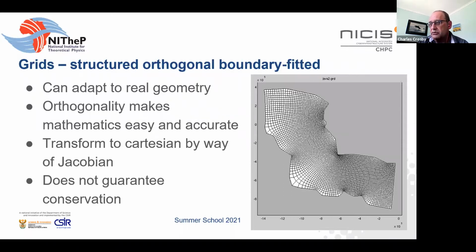So I was talking about this maybe being two coastlines with a piece of water in between, or some kind of two-dimensional flow channel. That's not really relevant at the moment. The point is, this is a single block orthogonal boundary fitted grid. So you take those words individually. It's a single block grid, just like the previous one was. So it's got a certain number of I dimensions and J dimensions. It's orthogonal. It's not rectilinear, but the grid lines cross each other at 90 degrees.